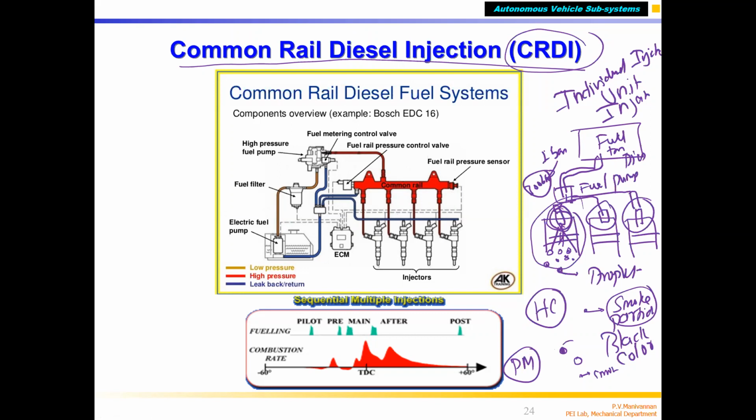Now, this particulate matter, partially burned carbon and hydrocarbon, if you inhale it, goes inside your lungs and deposits there, and it can create cancer. That is the problem with diesel engines, correct? In a diesel engine you also get NOx, nitric oxide formation, because the combustion temperature is very high. Generally, combustion temperature is more than 1200 degrees centigrade.